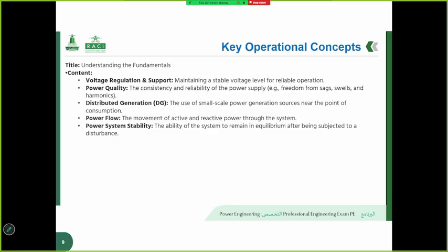A power flow study calculates the voltage, current, and power at every bus node in the system under a given set of conditions. This analysis helps engineers understand how the grid is operating, identify potential bottlenecks or overload, and plan for future expansions. It is a fundamental calculation in both steady-state analysis and dynamic simulations.